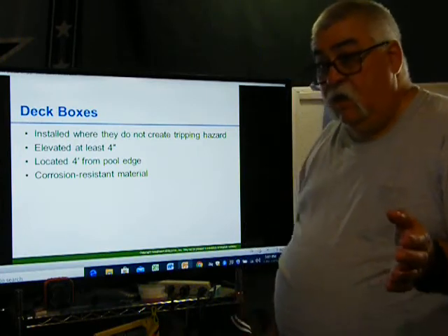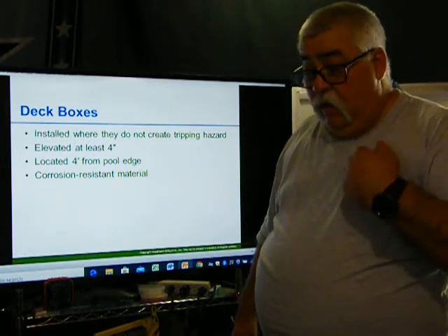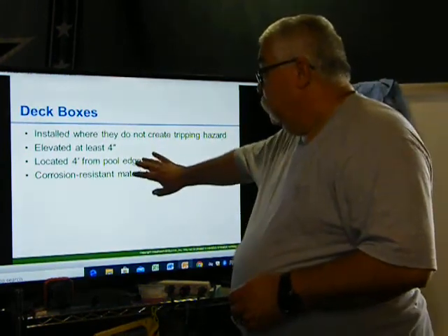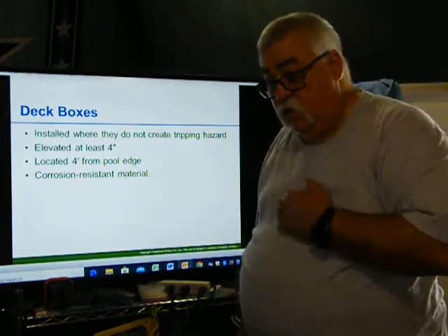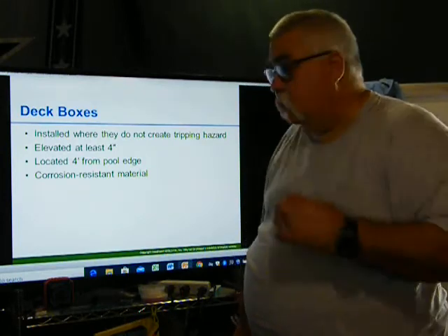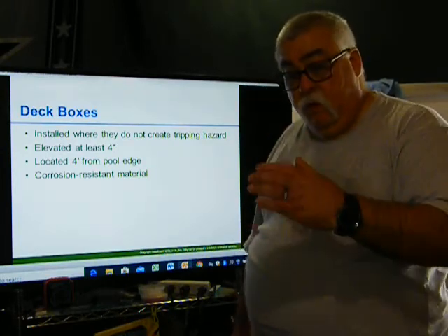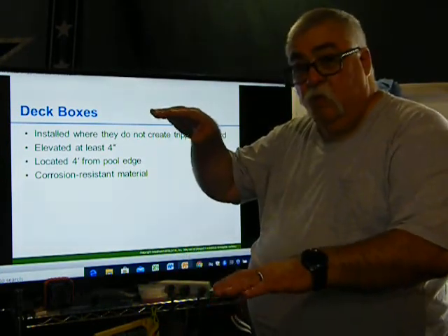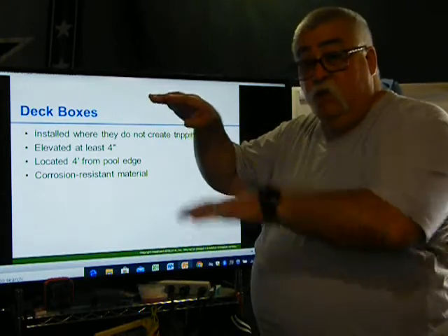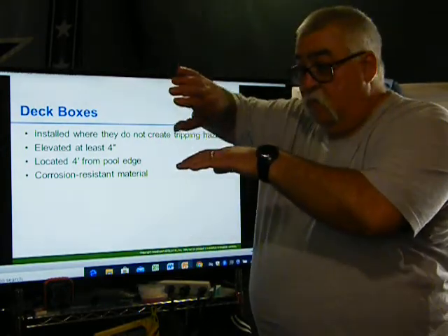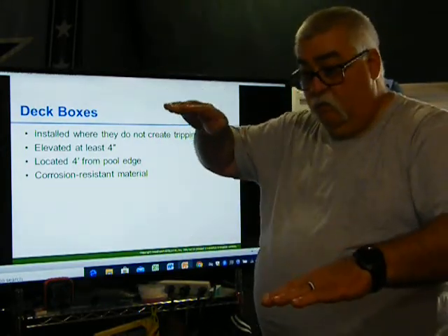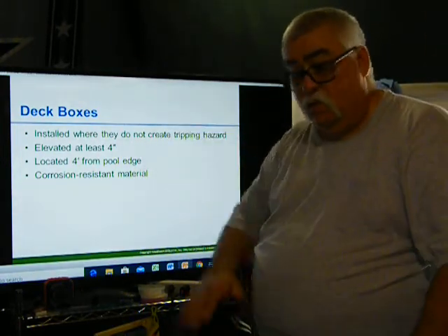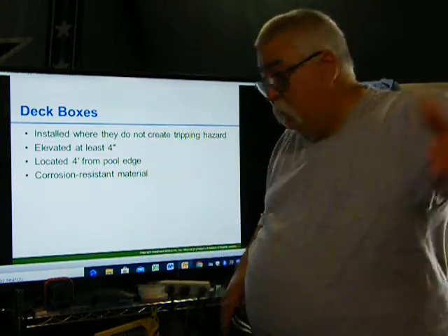The idea is to create safety; I always thought about getting electrocuted. One of the things they had, the local jurisdiction, wasn't 18 inches, it was 12 inches. So whatever box we put in had to be 12 inches above the water level. So if the water came up, it wouldn't get up to that box. Here's my box with my connection, here's the water level, and I'm 12 inches above. So the water level never went up to it, or people splashing. Guess what? The water level moves that pipe.